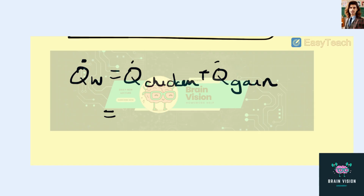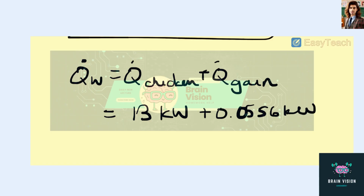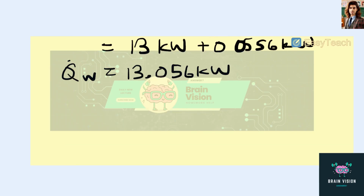So this total Q dot water will be equal to 13 kilowatts plus the 200 kilojoules per hour that was given in the problem statement, and that is equivalent to 0.0556 kilojoules per second, or 0.0556 kilowatts. That gives us a total heat transfer to the water of 13.056 kilowatts. That's Q dot water.